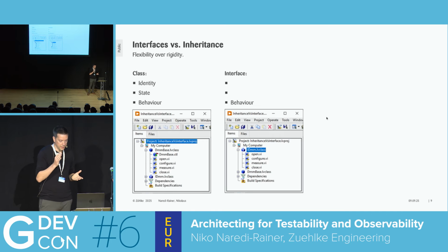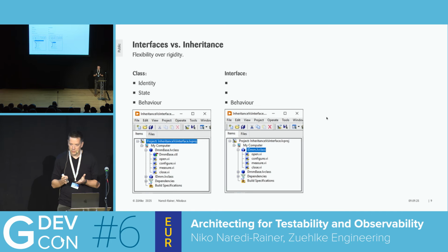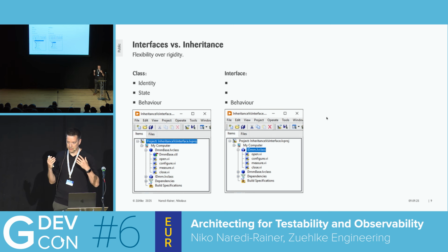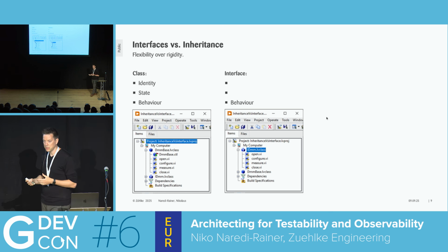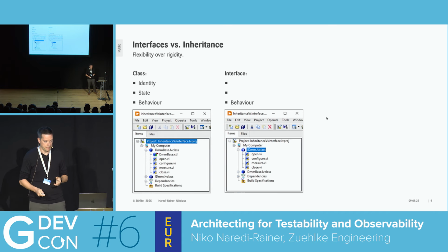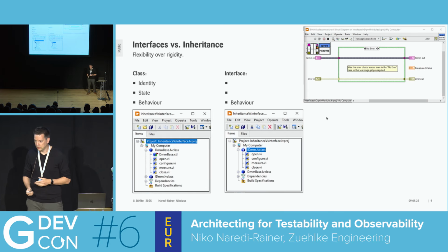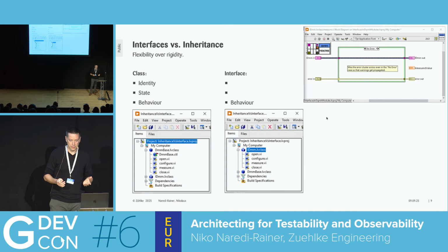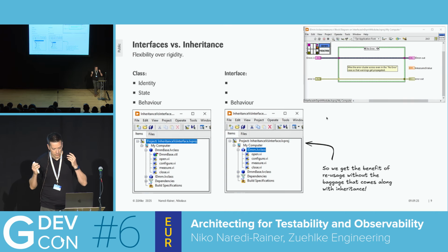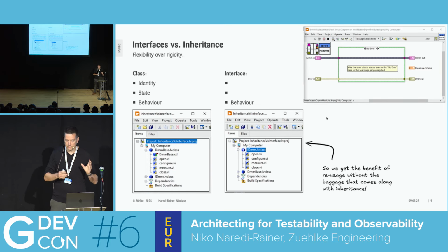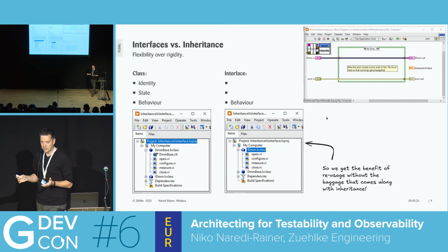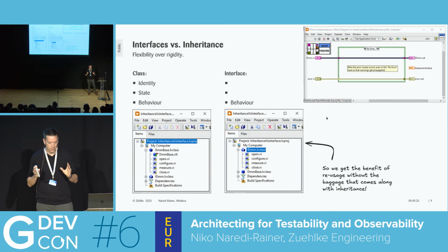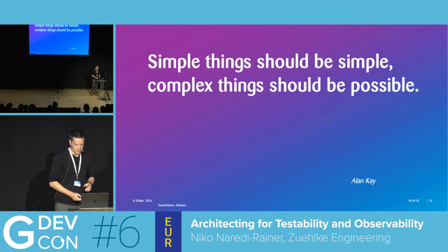And the same is true somehow in the LabVIEW context. What that means is basically you're coding just against a list of VIs and their connector panes. So there's no code inside, whatever. When you take a look into that interface in here, there's really no useful code in there. So basically your test sequencer, your DQMH module, they just execute the measure VI, and they don't know what is behind. If it's a real implementation, a fake implementation, they really don't care.